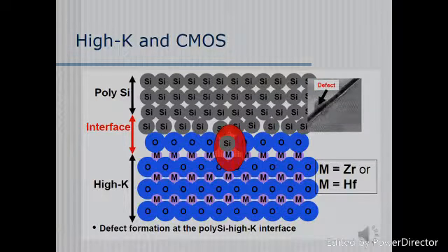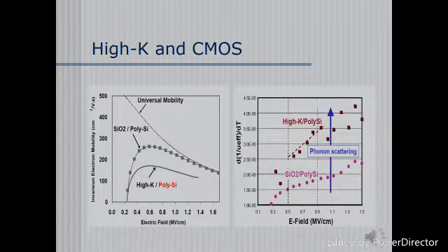The first problem in CMOS technology with high Kappa dielectrics started with charge trapping. Charge trapping has the ability to change the threshold voltage of a transistor over a period of time and can therefore cause major changes to a transistor's properties. The traps' levels of energy are very large and contribute to tunneling. It is caused by uneven surfaces of the dielectric when metal organic chemical vapor deposition is used. By depositing a single layer of atoms like in atomic layer deposition, we can create single atom layers that are uniform throughout the surface.